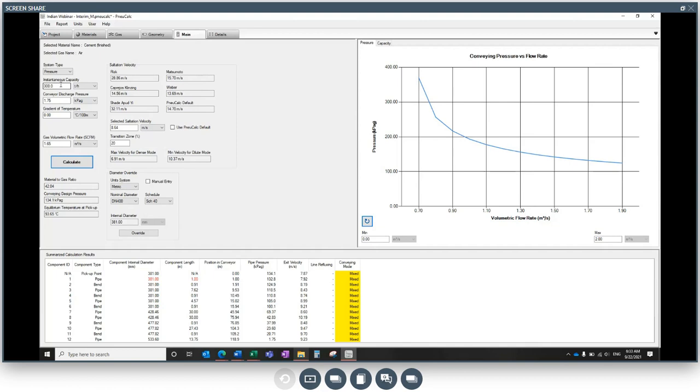With blow tanks, as we alternate from one to another, there's a small loss of efficiency because during that brief moment, the pneumatic system is actually not pushing material into the pipeline. So we need to increase our instantaneous capacity to make sure that when we push material, we push a little bit more, and over a period of an hour, say, we get 300 tons per hour.